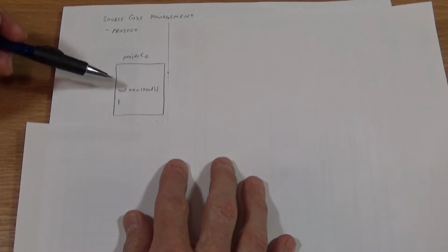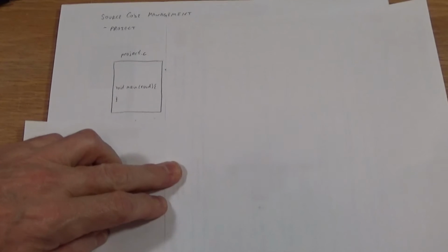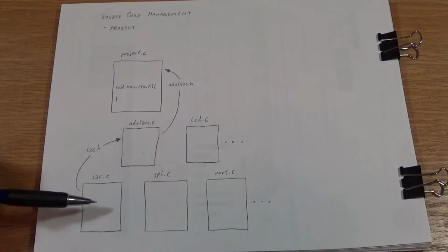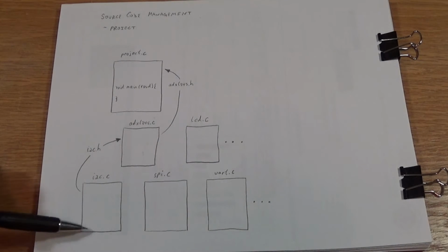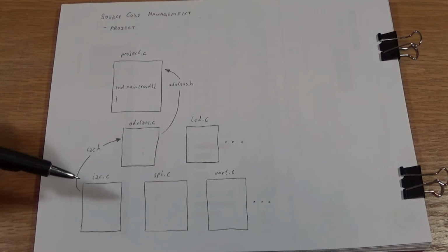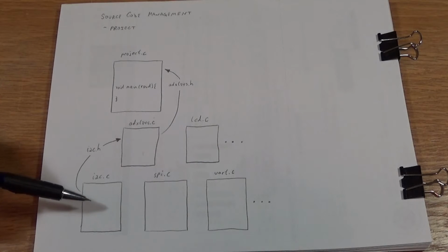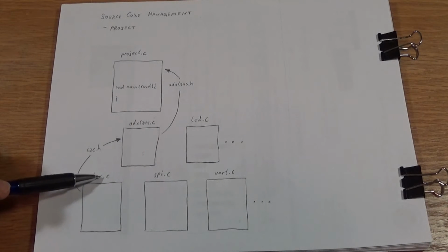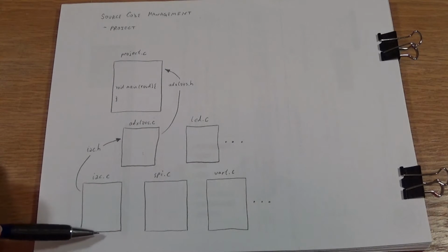Now let's look at it a little differently here. Whoops. I'm going to bring up a lot of confusing stuff here. There are a lot of these little breakout board sensors that you can get: accelerometers, magnetometers, compasses, gyroscopes, pressure sensors, temperature sensors, etc., etc. Most of them will communicate over the I2C communication bus.